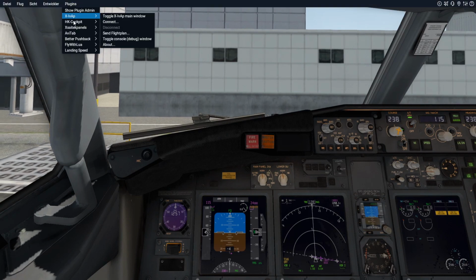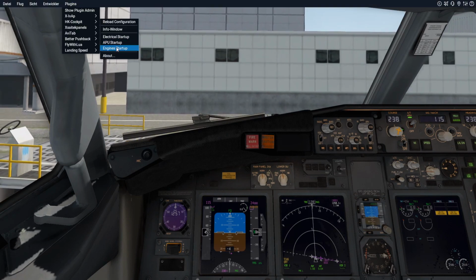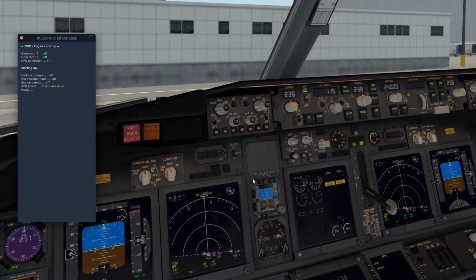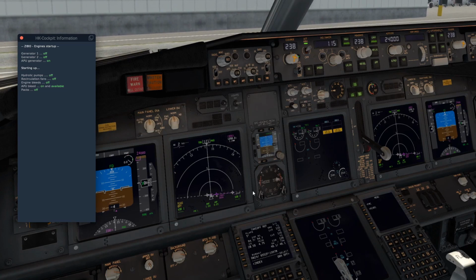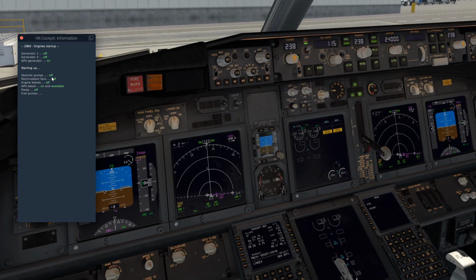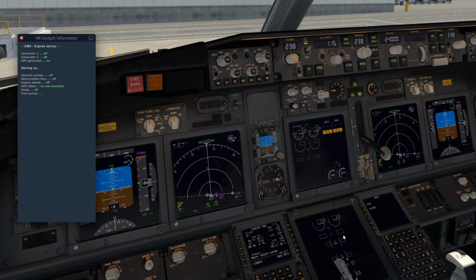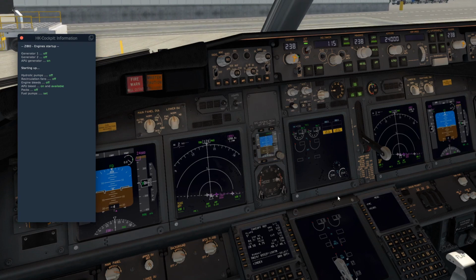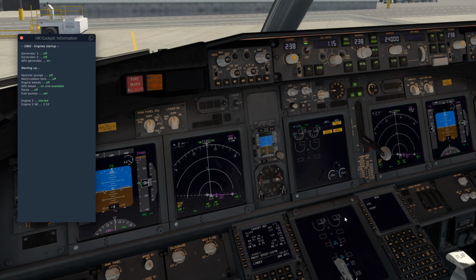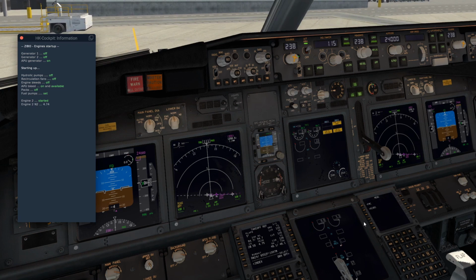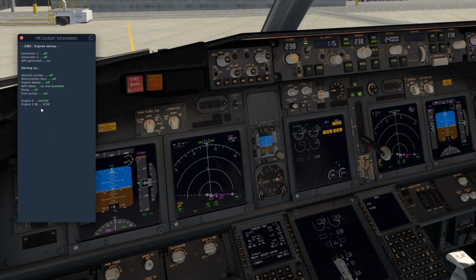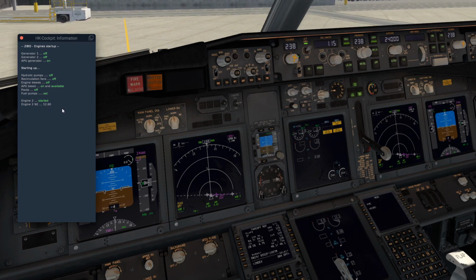And now it's time to start the engines. So set the overhead panel as required to start the engine, opens the fuel pumps, and then starts the engine. As we can see, the plug-in now waits for N2 to become 25.